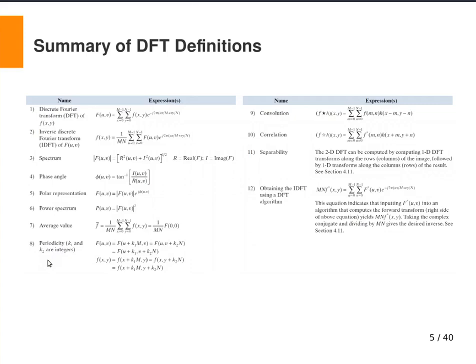We also talked about the periodicity of both the discrete Fourier transform and its inverse, and how it can make some of the analysis a little bit more challenging, especially when we talk about convolution. Instead of having regular convolution, we had to perform circular convolution, and to make sure that there is no error in the circular convolution, we had to have extra padding on the signals to avoid any overlap and error in the calculation of convolution.